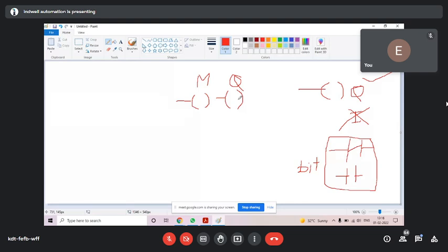So you can say in your program, if output coil is on by any means, physical output terminal Q0 will get high, and the connected physical output will also get on. So you can say output has physical existence, correct?